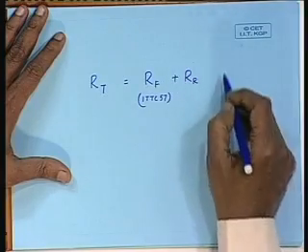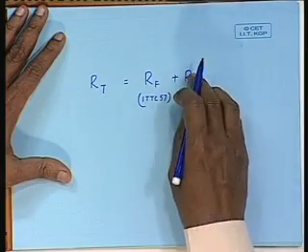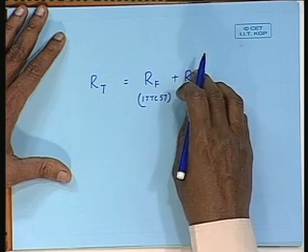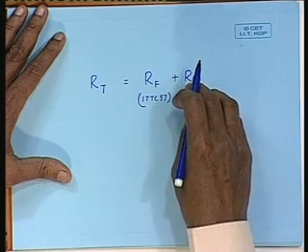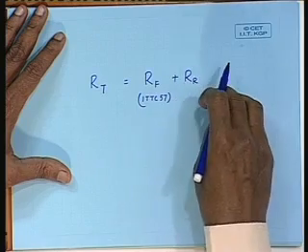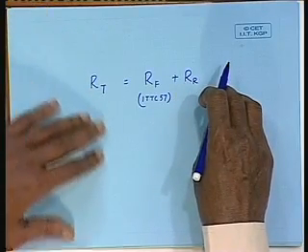Similarly, when we talked about pressure resistance, we said the pressure resistance is equal to the wave making resistance, but there could be some interference between the frictional resistance and pressure resistance, thereby giving something we call viscous pressure drag. All those components are included in this residual resistance, the main component of which, however, remains the pressure resistance or the wave making resistance. Have you understood now?